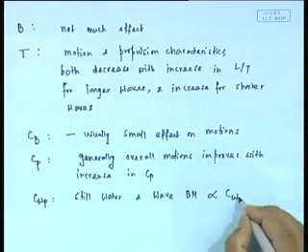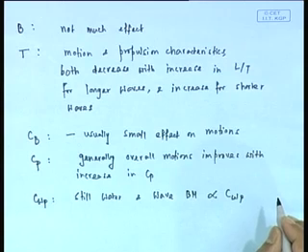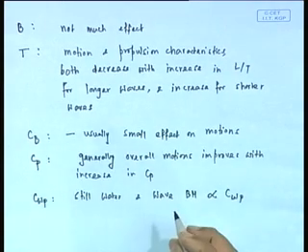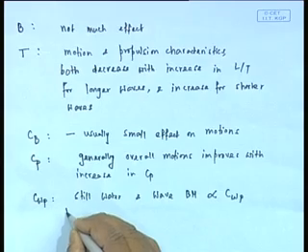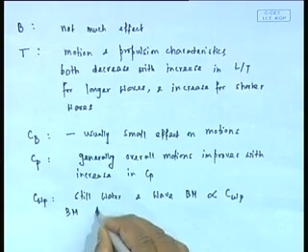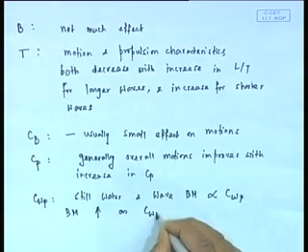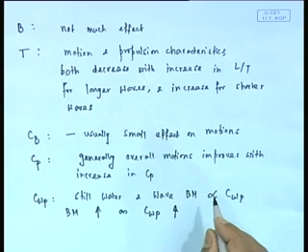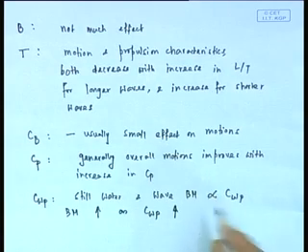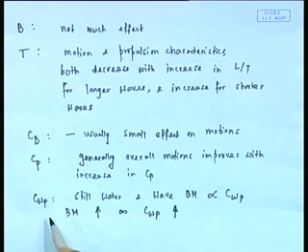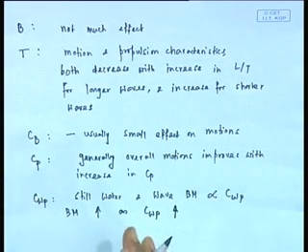The waterplane area affects primarily the bending moment. That makes sense basically, because if the waterplane area comes down, you have a much smaller restoring force, so a larger bending moment comes out. Okay.